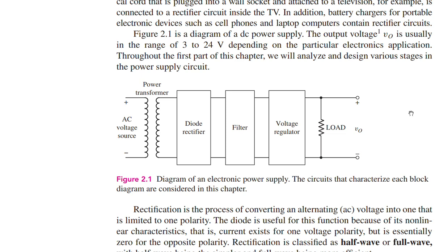But the point is that the input voltage at the input of the rectifier is still a purely AC signal. The DC level of this voltage is 0. When the signal passes through the rectifier, it only allows the positive half cycle to pass, or negative, depending on the way the diode is connected.